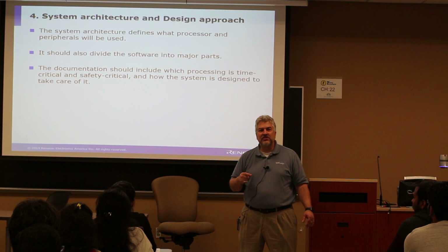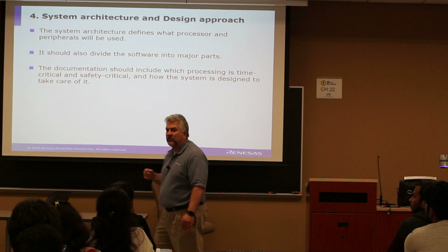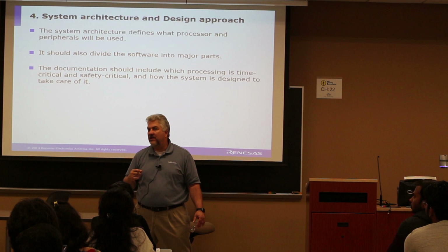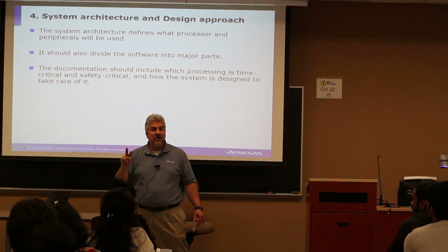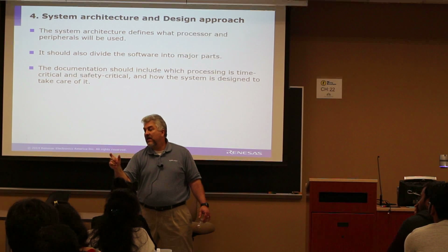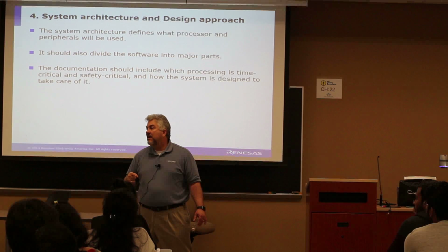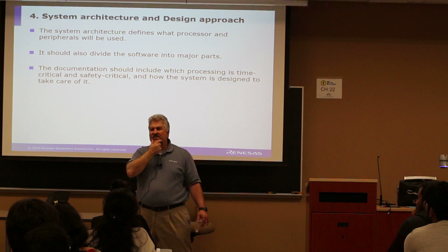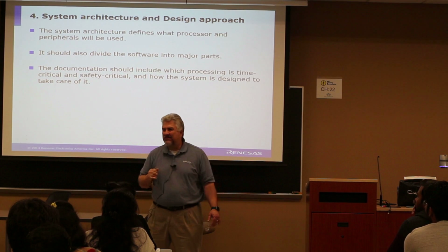Revolutions. Yeah, so we have to find some way to detect what those revolutions are per second, right? For the distance, right? Or you have to weigh, actually there's 2 aspects of this, right? Speed. You have to have a sensor that attaches to the wheel to know exactly how many times you revolve. Do you think an accelerometer will do that? Rotary encoder. Accelerometer may not do that, right?